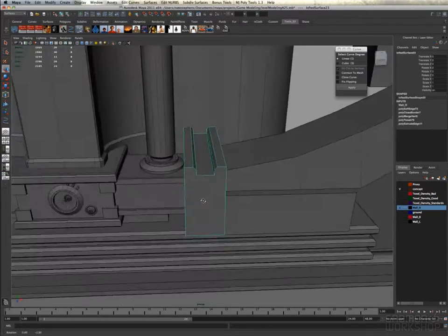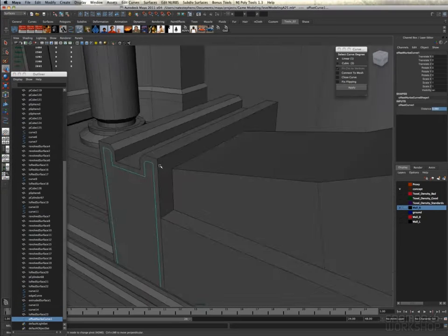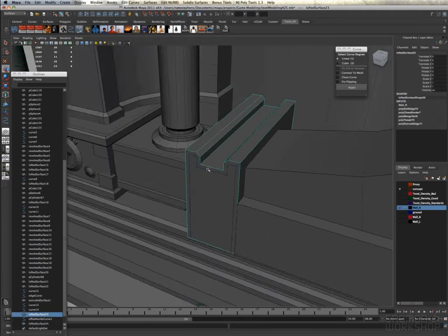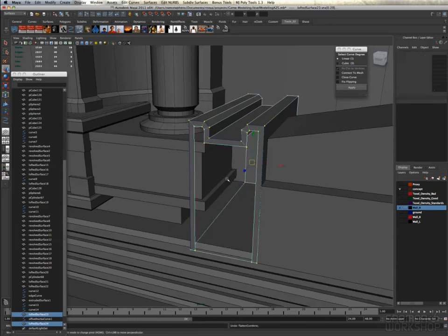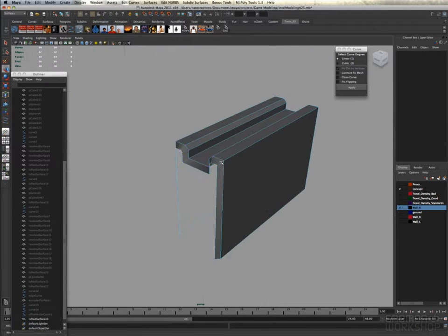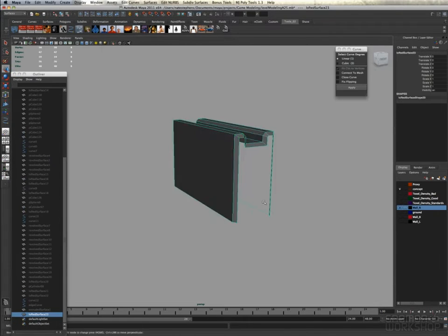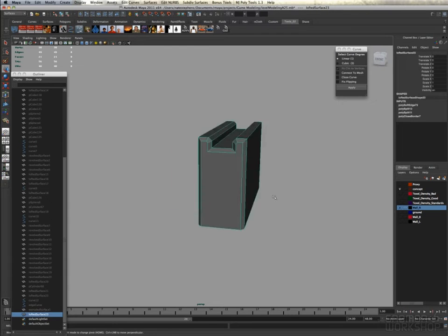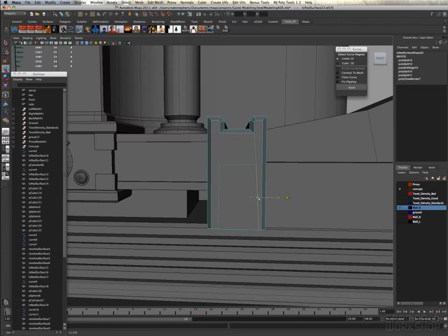So I've made an object here, filled in the holes. This object, like so many others, was started with a curve, and now I'm copying the curve and offsetting the curve, and using that offset to create a loft, and then welding it all together and filling in the holes. Hardening these edges here so that we have a nice beveled sci-fi look, and then filling it in and using the split polygon tool to add some more details.